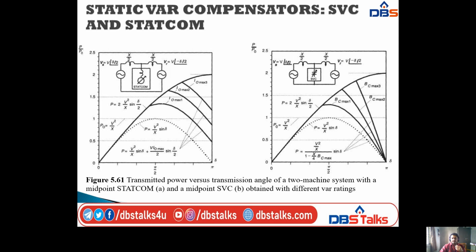Here I am taking a total of 4 curves. Of those 4 curves, one is in dotted line representation. That is the normal power, P equal to V squared by X into sin delta. Like that we are drawing the characteristic diagram.